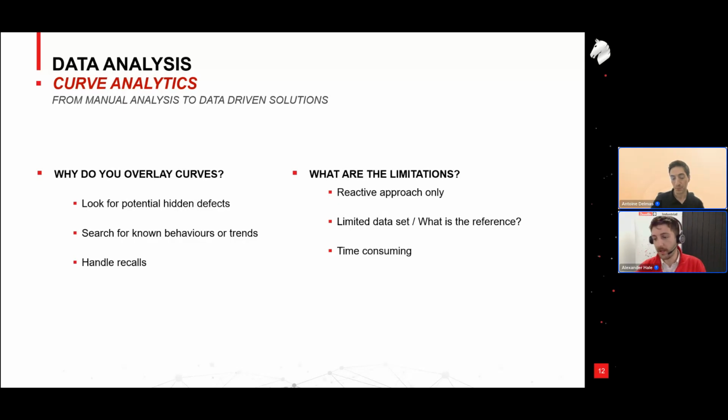Just to say one thing, Antoine, like you say, 5,000 curves sounds like a lot, but for someone with a very fast takt time, 5,000 curves is nothing. And we know that rundown can be affected by temperature, for example. So what happens if the 5,000 results you choose are in winter versus summer? It's going to look different. What happens if it's a molded part and the mold tool ages over time? There are so many reasons why just choosing 5,000 results is flawed. We see that, right? Yes, absolutely.